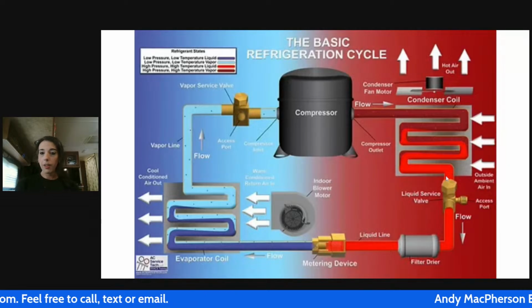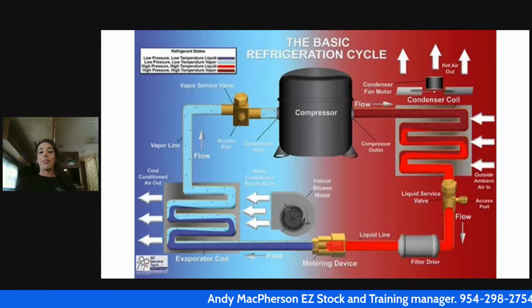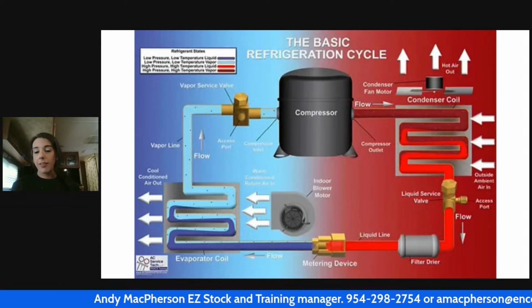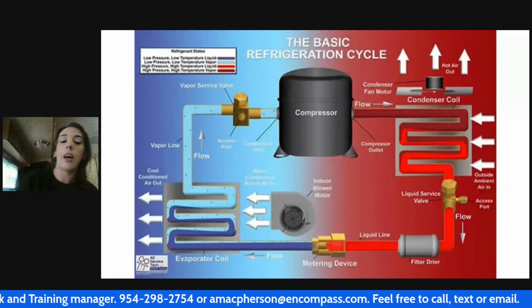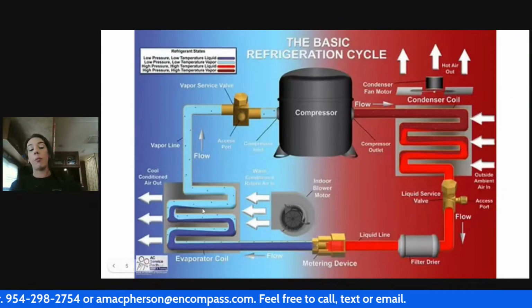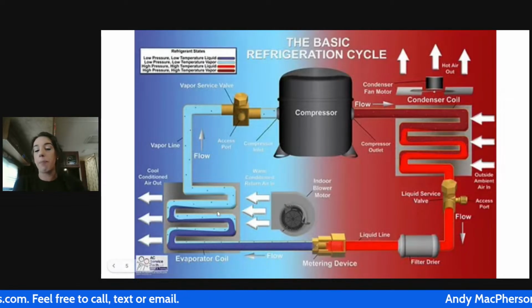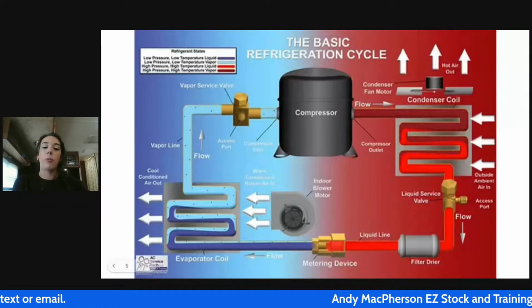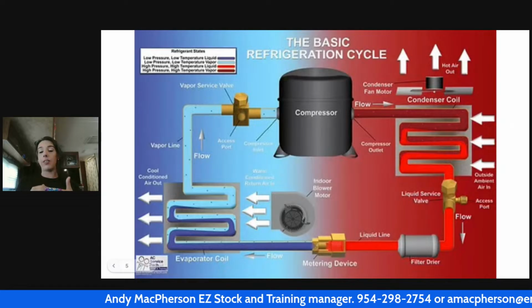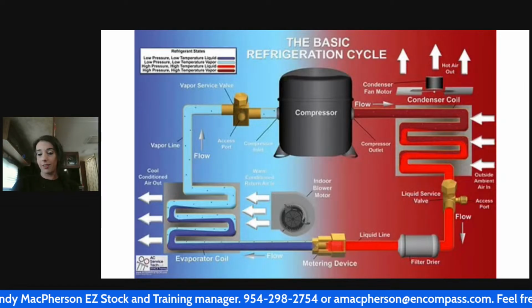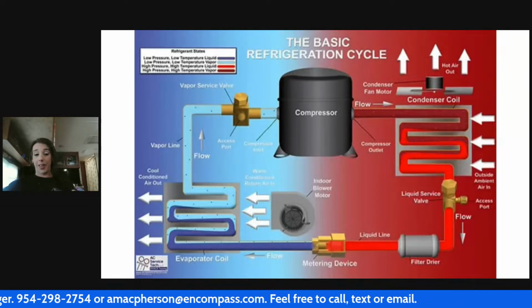So then we talk about, just real quick, superheat and subcool. Okay. So the definition of superheat is the temperature at which we are above saturation point, in the evaporator. If we are saturating at 40 degrees, say we're saturated as a vapor at 40 degrees, and we have 10 degrees of superheat, all that's telling us is that 10 degrees more than saturation is what our unit is running at. And that's really important because if it's high, that tells us our evaporator is empty.